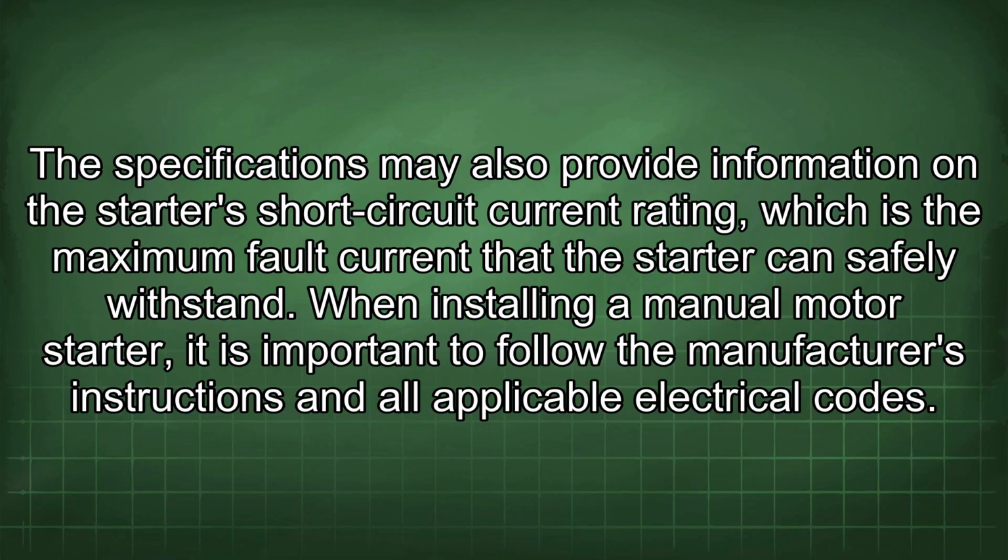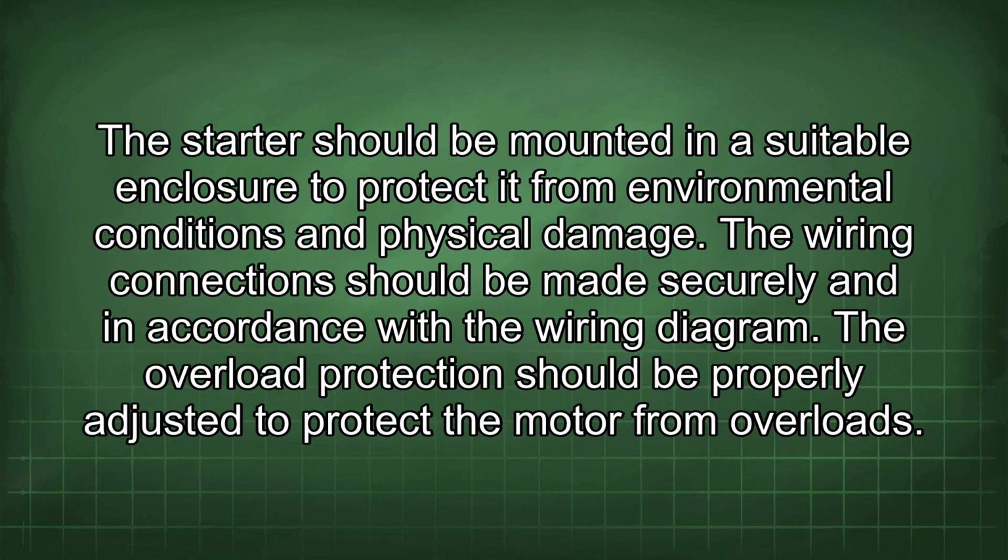When installing a manual motor starter, it is important to follow the manufacturer's instructions and all applicable electrical codes. The starter should be mounted in a suitable enclosure to protect it from environmental conditions and physical damage. The wiring connections should be made securely and in accordance with the wiring diagram. The overload protection should be properly adjusted to protect the motor from overloads.